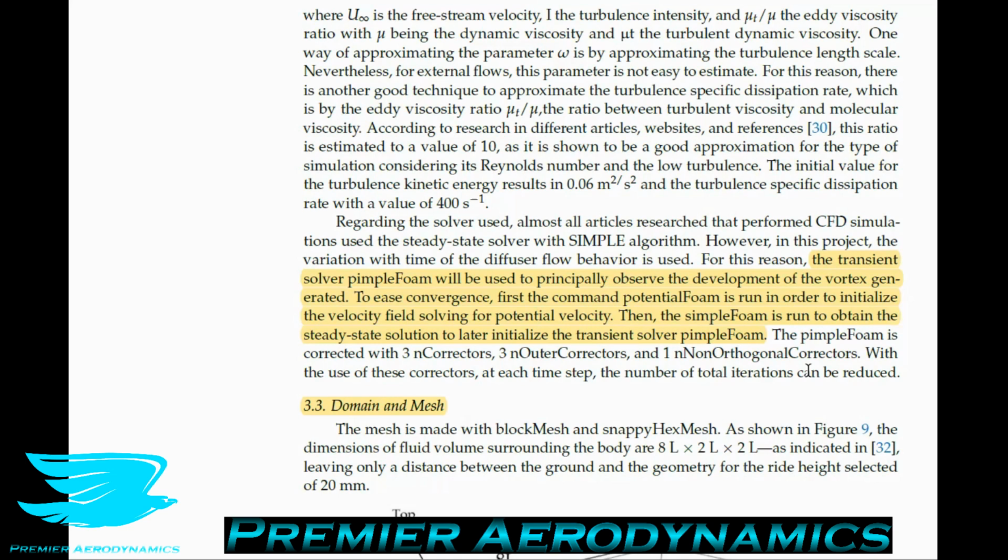So instead of going from the initial conditions, you now have a solution that you've run through this potential solver to be a bit further ahead along the convergence path. Then from there, they actually use simpleFoam to run it a bit further to get a better initialization. And then they finally use pimpleFoam, so the transient solver.